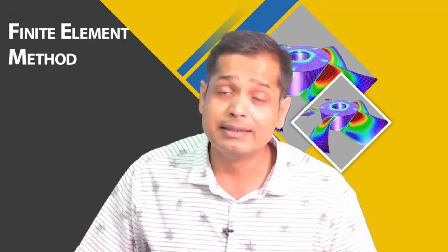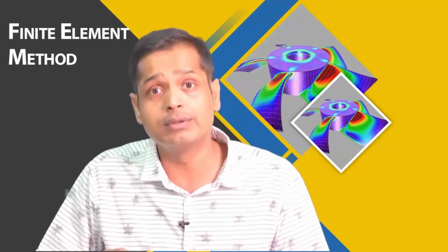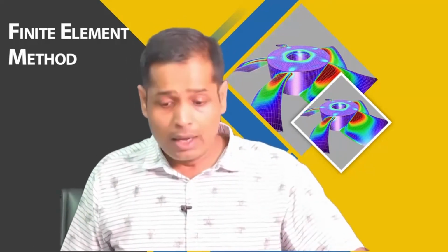Hello everyone, this is the second lecture of this week. By now we know how to construct shape function for quadrilateral elements, and we had a detailed discussion on that. But as far as triangular element is concerned, we know only how to construct shape function for a linear triangle, 3-node triangle. Now today and next week our topic of discussion is how to construct shape function for higher order triangular elements. So let us start.